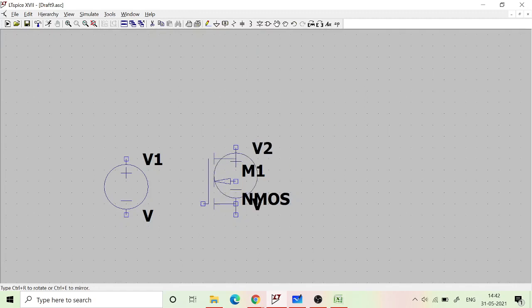So I left click one time, and then I click it again, then I right click, so it will go away. You can place as many of the same component as you want by left clicking, but if you want to stop doing that, then you right click.